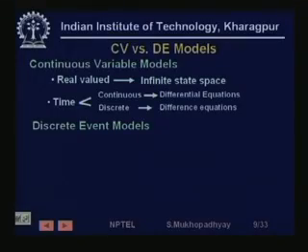Contrary to this, in discrete event models, which we are going to use for sequence or logic control problems, typically the values of variables that we'll consider will be finite. So let us say a typical example is on, off, or some tank level: low, medium, high. So we are not interested in knowing how many meters. We are only thinking that the tank level could take one of 3 symbolic values. Each of those symbols actually represents some kind of an analog level value range.